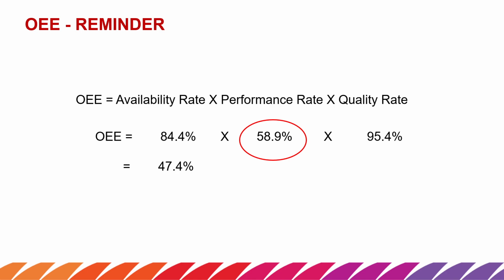Performance is the machine capacity or machine standard run cycle time. If machine is able to produce number of units in that X time, how much machine has actually produced, that is the performance rate. And quality rate is the percentage of the product that is 100% compliant as per quality standards. So for OEE, we multiply all these three and we get this number: overall equipment effectiveness.